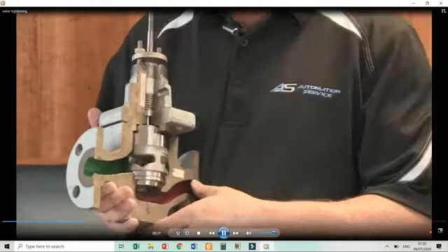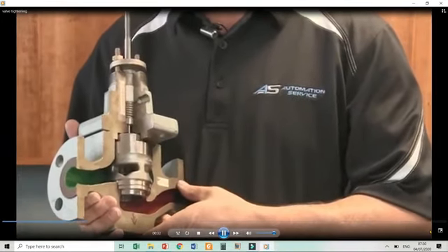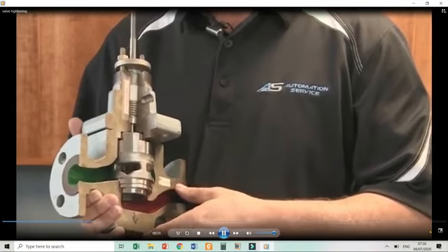Over time, the packing will wear in, relax or loosen up with process temperature or even seasonal ambient temperatures and begin to leak. Any process fluid that leaks out of a valve can be costly, can be messy, and maybe even harmful to health and environment. The most important thing is to catch the packing leak early and address it before it has a chance to further cause damage.